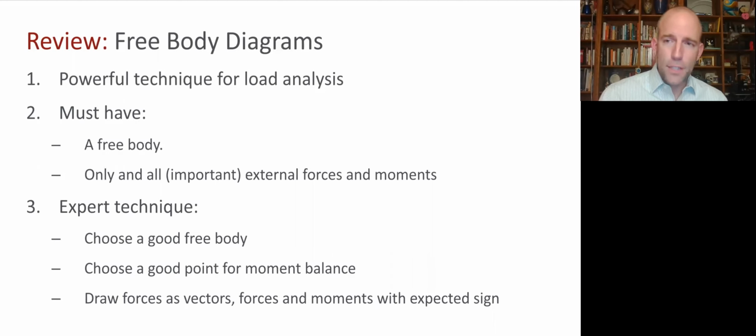And I know that they teach students at the beginning to draw all forces as two components and a moment, but as you become more expert, it becomes more helpful to draw your forces as vectors and your forces and moments with the sign that you expect. So they kind of point in the direction and kind of look like how big you expect them to be when the analysis is complete. That can be very useful in making things go more quickly.